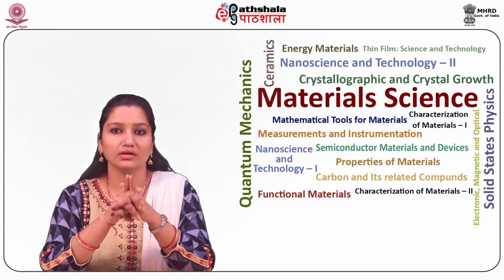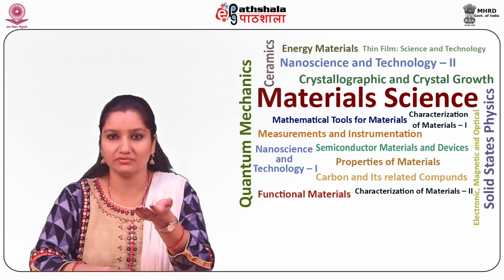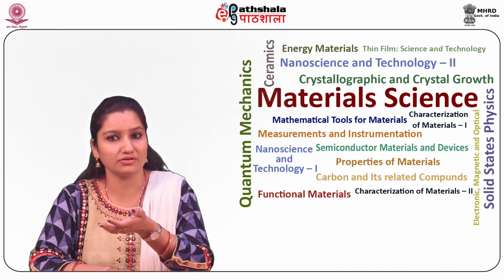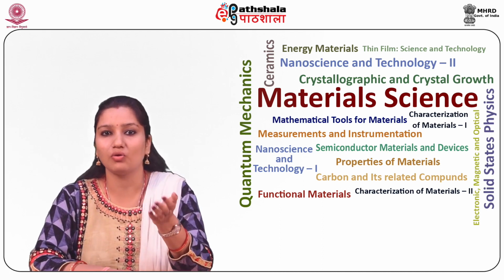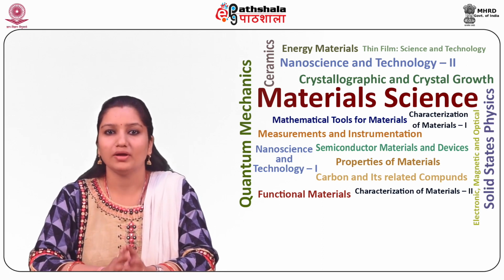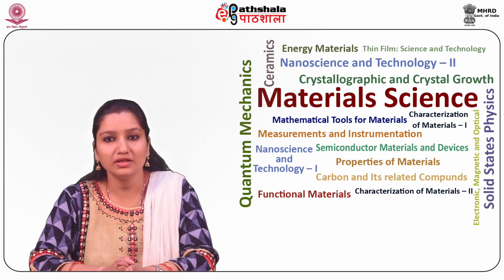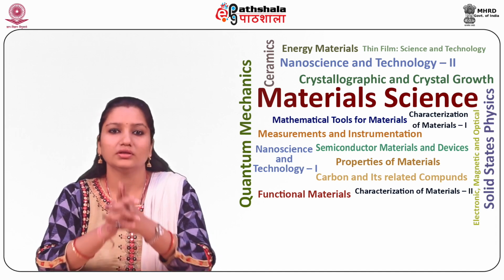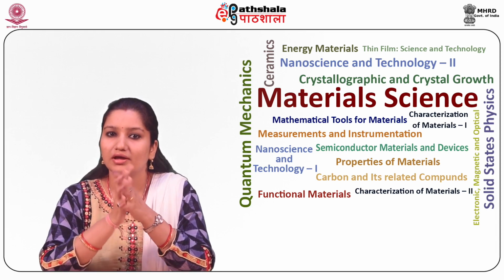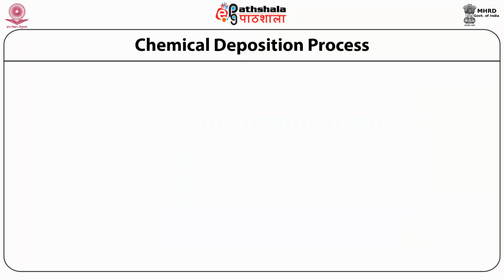Thereafter, the prepared homogeneous solution is treated with suitable stabilizers for aging and capping agents to obtain the desired controlled shape. In the CSD technique, various combinations of precursor, solvents and stabilizers have been employed in the production of thin films. Their unique properties and reactions affect the preparation process and determine the final product. Therefore, essential features of precursor and solvent need to be highlighted.